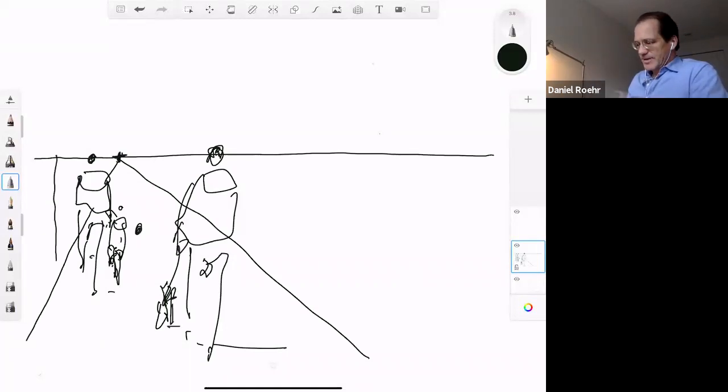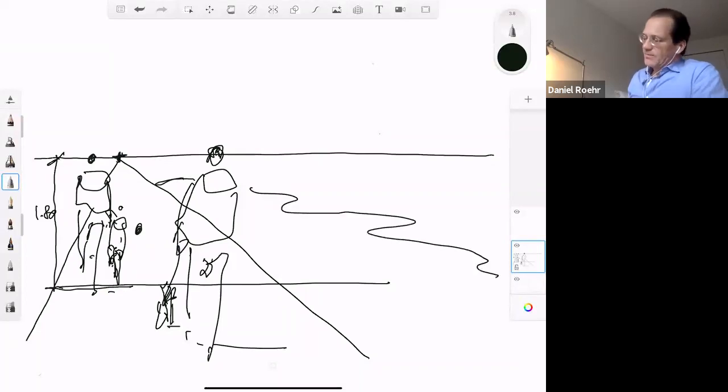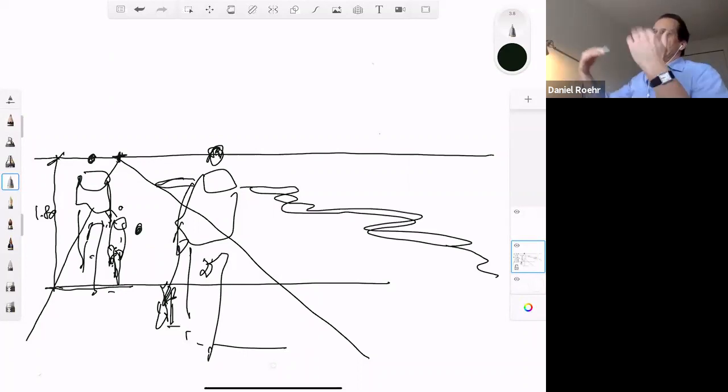One thing you know at this point, just to repeat this, this is about 180. So the footpath, if you would tilt this person, is about 2 meters wide. So you can actually use the human scale to scale the drawing. And then put in slowly what kind of form your planting is. And one thing I can always say is keep the outline flat. Don't make it too steep. Otherwise, it looks like the drawing is falling out of the paper. The flatter, the better. And the further back, the less information you can see.